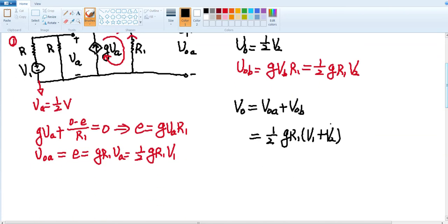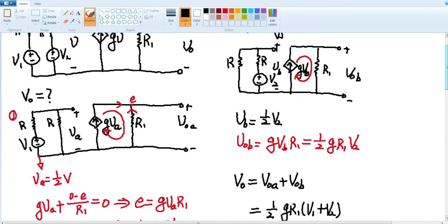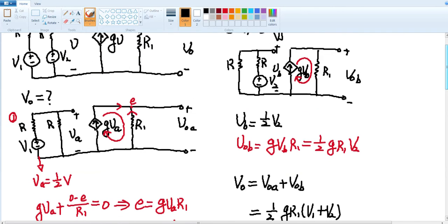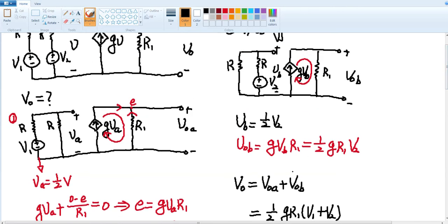Let's look at this final output. You see it's equal to V1 plus V2, of course, multiplied by some coefficient. You can imagine you can utilize this circuit as an analog adder. Basically, you add voltage V1 with V2. Previously in the lab, you also learned you can directly utilize a resistance network to make an adder, where you add the signals from different channels.